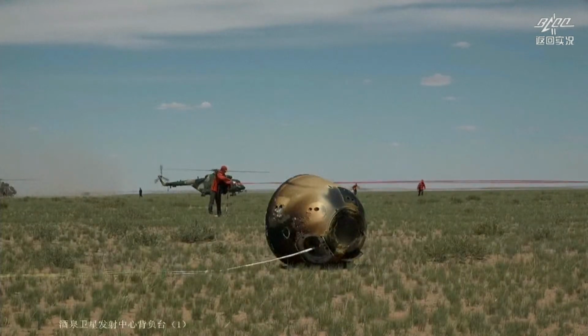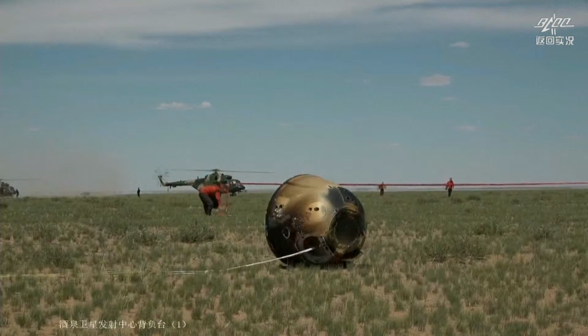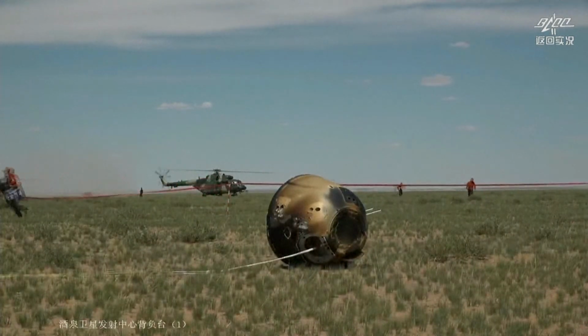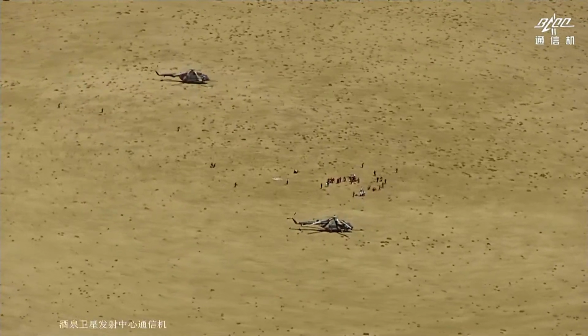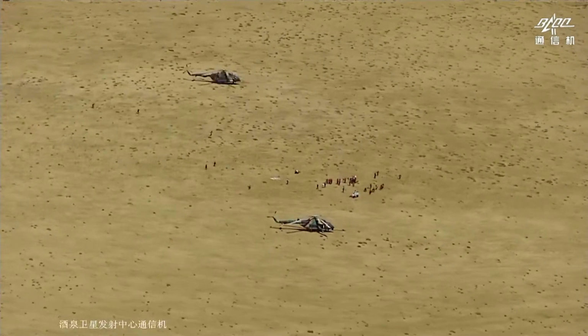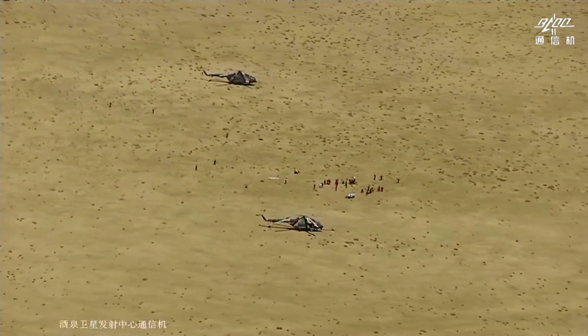And another thing why it is inclined is because in the design, the center of its mass has a deviation from this cylindrical axis. This is to have control, to have an angle of attack during the re-entry to make it possible to control the changing direction of the lift.